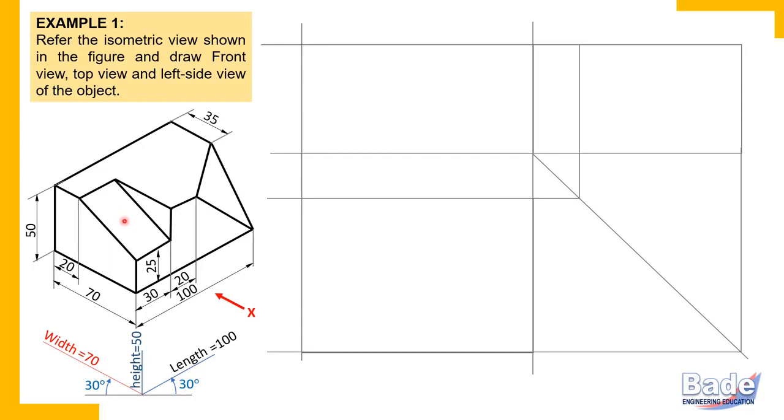If a surface has an edge parallel to the length axis, and the length axis is perpendicular to PP, in the profile plane you get height and width. So the third axis, length, is perpendicular to PP. So if a surface has an edge perpendicular to PP, it means that the entire surface is perpendicular to the profile plane. And if a surface is perpendicular to the profile plane, then it appears as a line in the side view.